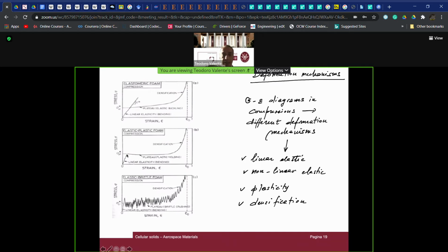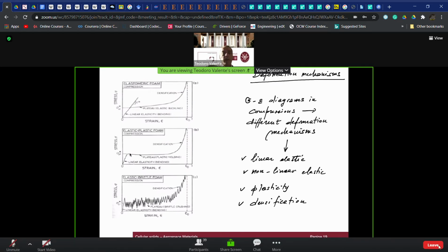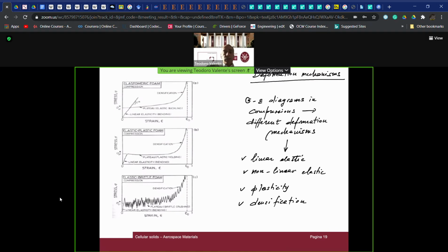And also in this case, when we reach plastic yielding, we have, for at least something near zero increase in applied compressive stress, a very relevant increase in strain up to, again, the final limit, which is again defined as epsilon d, strain d, in which densification due to recovery of all the voids inside cellular solids starts to happen.